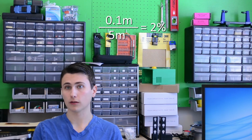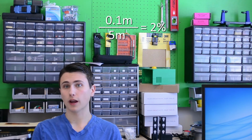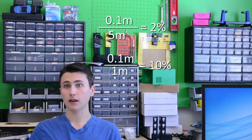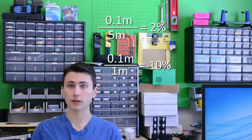If this were 1 meter with a variation of 0.1 meter plus or minus, the thickness would have a tolerance of 10%. Therefore, it's easy to see a reason why the larger value capacitor with plates closer together might have a larger tolerance if it's near the limit of the manufacturing process. It's also reasonable to conclude that the reason why we can't purchase a 100 microfarad 0805 capacitor with 1% tolerance may simply be because nobody can reliably manufacture them with yields high enough to be profitable.